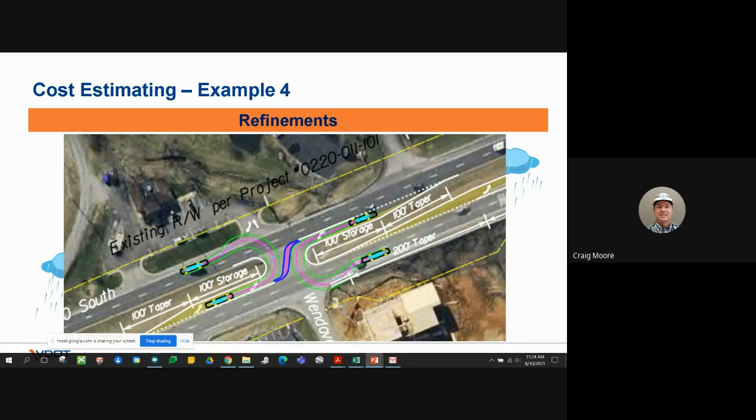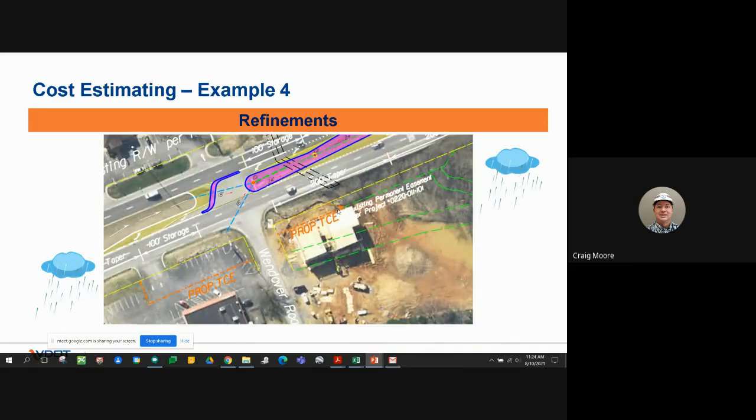So we're including that temporary construction easement, because that's a risk: until we have an actual detailed survey, we don't know to what level we would be impacting that property. So we need to show that temporary construction easement, same as we were doing for our stormwater drainage over here, being able to have the equipment access the site. We're also needing to do it over here because we may need to do some shoulder improvements to be able to adequately accommodate a school bus turning there.